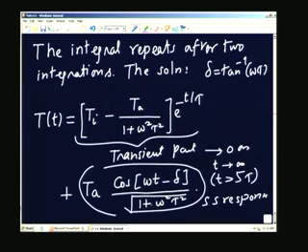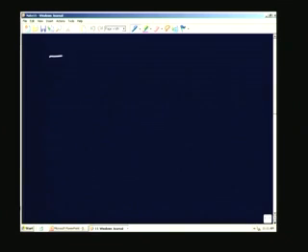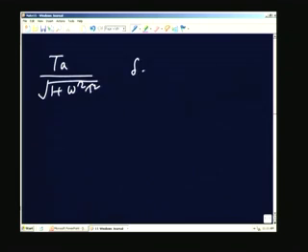And the coefficient is T a divided by the square root of 1 plus omega squared tau squared, which is smaller than T a by a factor greater than 1. Therefore, the amplitude is reduced. Therefore, we say that there is an amplitude reduction. So, T a divided by the square root of 1 plus omega squared tau squared, and delta is equal to tan inverse omega tau.